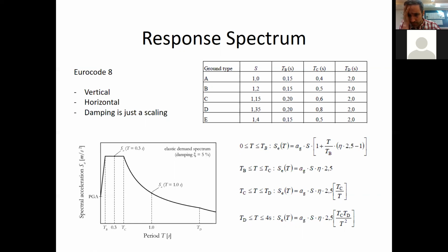Someone's asking for hints for the exercise in a real structure with a K matrix. There should be a printout which is hints for exercise C2. That should be available from Canvas, I think, on how to use it. Then in a real structure where K is a matrix, how are these spectra used? Well, then you have to look at each modal response by itself.